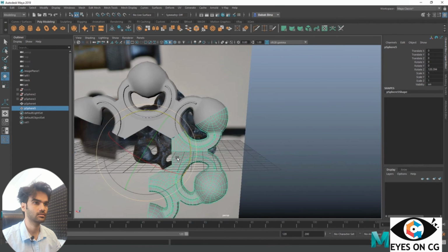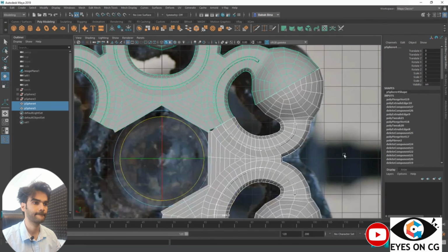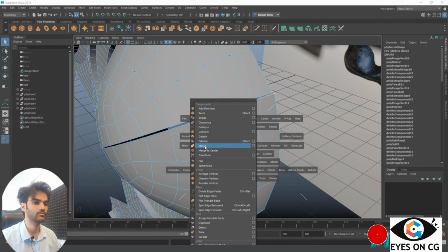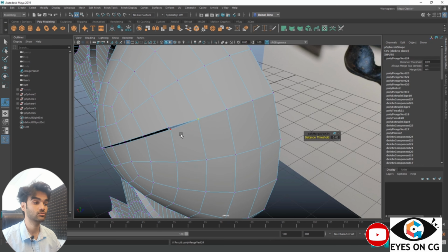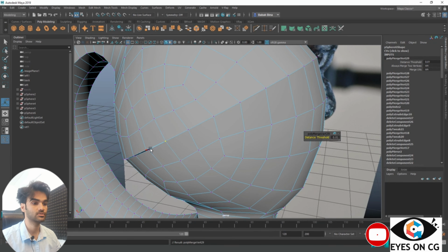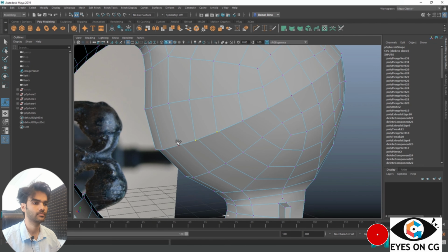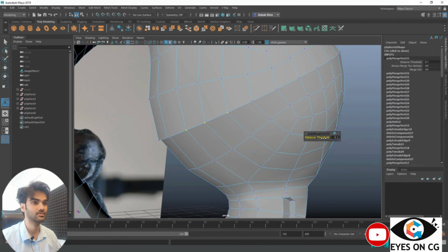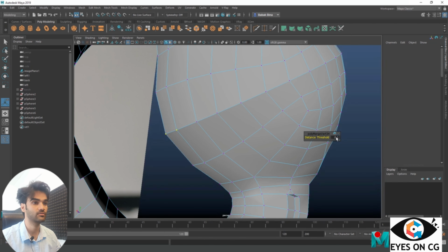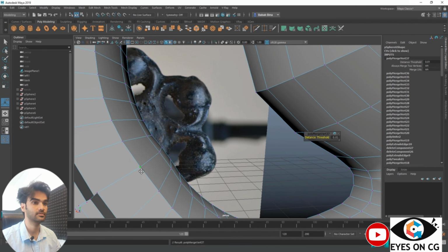Now here I'm selecting this, duplicating and rotating to 120 degrees. So as I duplicate that, then I need to merge these vertices. So select those vertices and merge to center. So all about this is just techniques, there's a workflow to create this kind of shape. So in this case we need to have something that looks nicer.